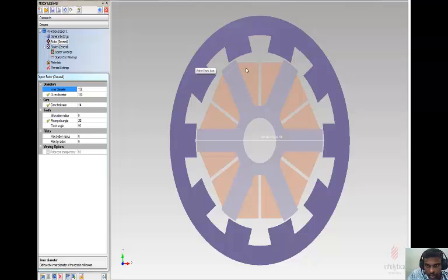Once you finish this, check twice that the input values you are putting in the column are correct, without any error. If you make any mistake, the field is going to be highlighted in red. For example, instead of 90, if you put 180 here, and the machine cannot have a 180 degree tooth angle, it is surely going to highlight in red, so that you may change it according to the correct design.